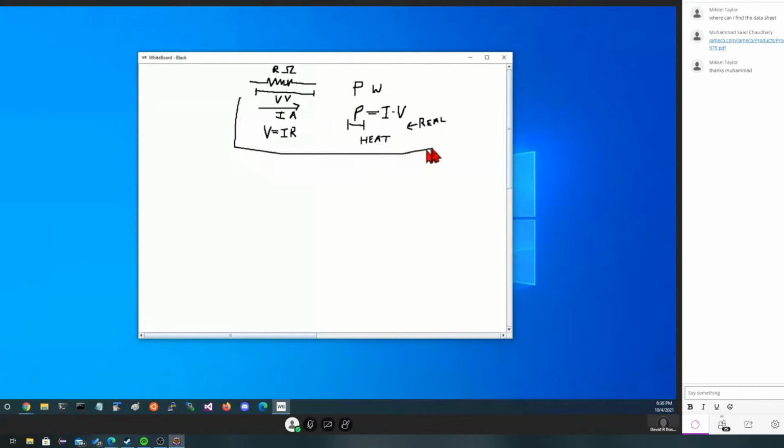So this we've gotten pretty good at. Now it's a steady state thing, and it really doesn't matter what we're doing with the resistor. If we were to put a sine wave through a resistor in terms of voltage, where it just followed some sine wave, at every point in time along that sine wave, we would see a dropped version of it in phase with it at the other end of the resistor. And it would follow Ohm's law, and it would follow a power law.